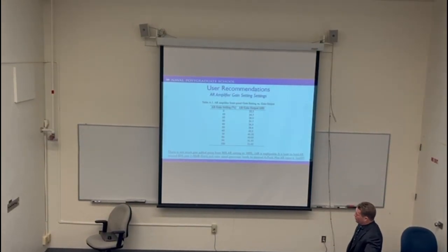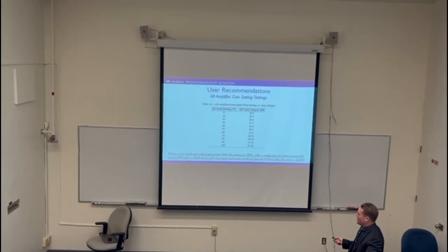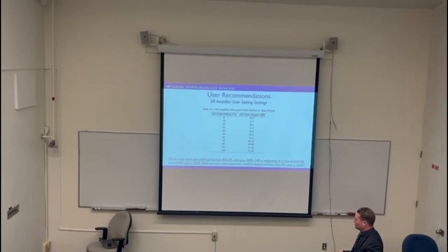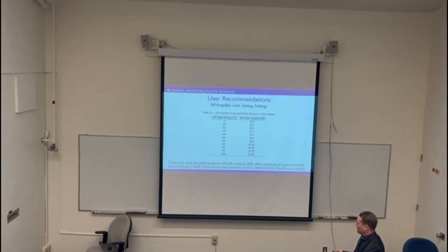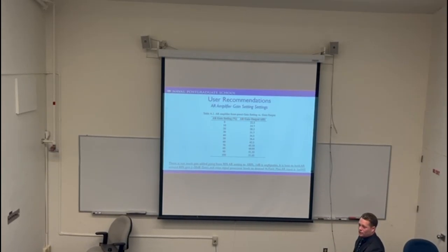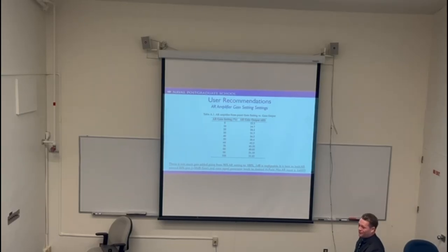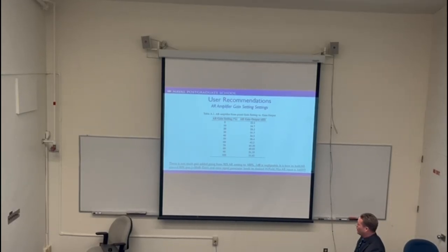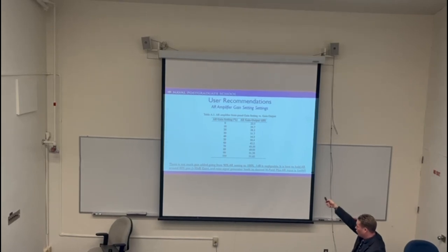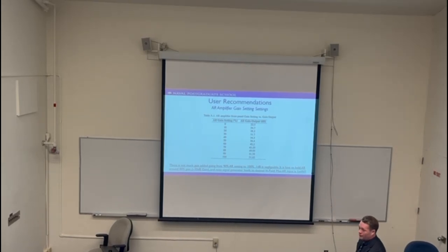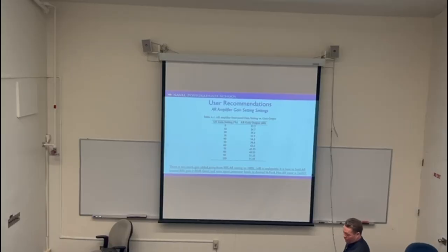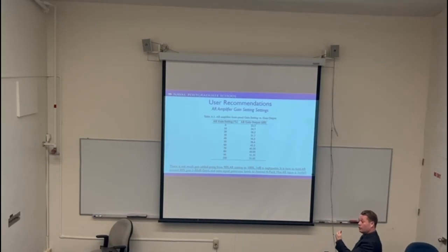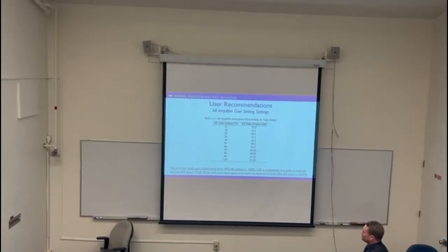So for just general feedback on the AR amplifier, what's interesting is you get to that 90% mark on the AR amplifier, and you go another 10% to your 100%, and you get like 0.1 dB. So it's quite negligible. It's good to know though, as when you're walking into this blindfolded. We had to back out what all these actual dB values were, because all that you have on the AR front is literally a percentage knob. So what is that? I knew that the max it could put out was 54-ish dB, and it was 100 watt capable, but I needed to precisely know what those dBs were.